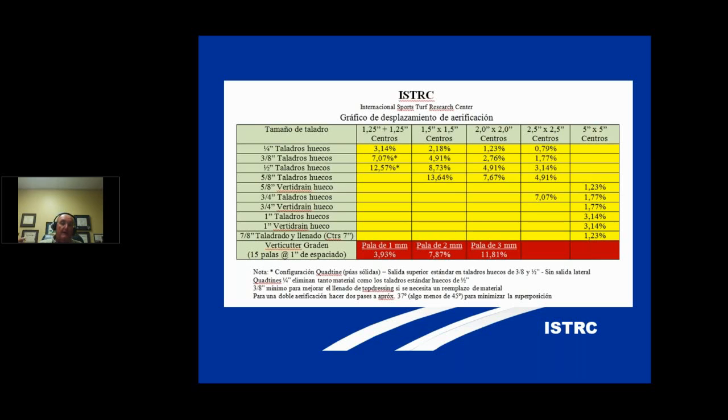And so I break that down. The first tier is 100 millimeters, the second tier is 100 to 200 millimeters, and the third tier is 200 to 300 millimeters. That way we can isolate any problems by where it actually happens within the soil profile. If you pull a PVC core and send it to a lab for a physical evaluation, they may come back with an infiltration rate of, let's say, 10 inches an hour. You don't know for sure where that 10 inches an hour is. It could be in the top, and more likely than not it is, but not always.